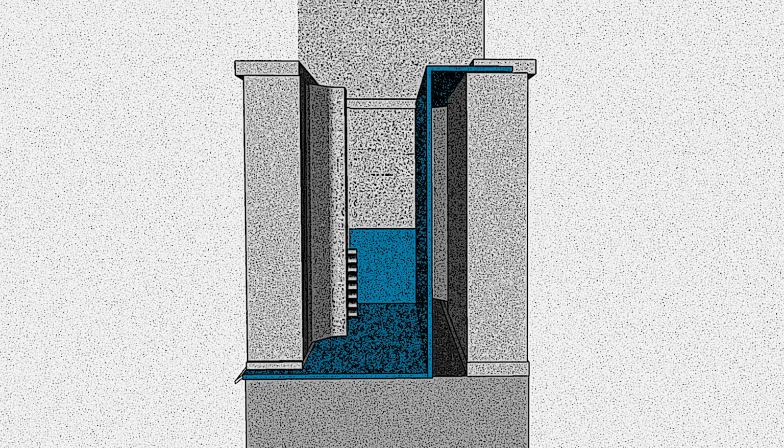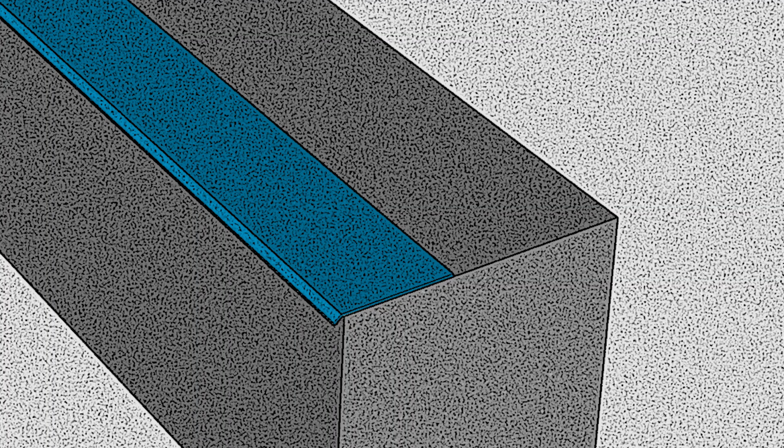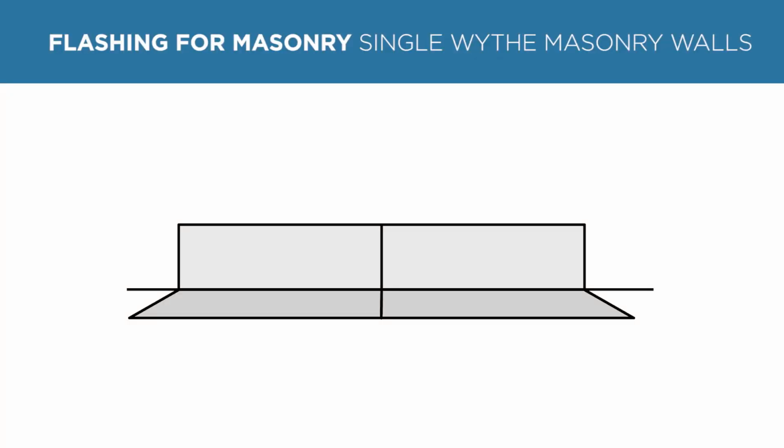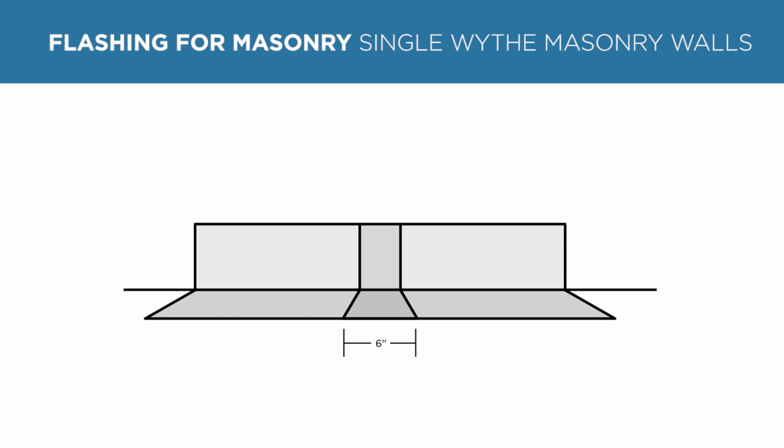The back of the flashing should be bent to embed in the bed joint of the next course at the interior face. Drip edge should be installed and sealed under the flashing. Any splices of flashing should have a minimum of a 6-inch lap and be sealed per the manufacturer's recommendations, or soldered in the case of metal flashings. It is important to ensure flexible flashing is fully supported.